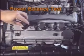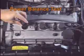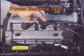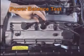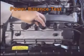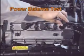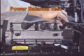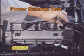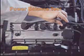For reference, when engine idle condition is not good, remove the high-tension cable from each cylinder one by one and perform power balance test, which compares the engine condition. Through this test, we can find the trouble cylinder, and we can solve the problem by inspecting the fuel system, ignition system, combustion chamber pressure, which may influence the combustion in the corresponding cylinder.